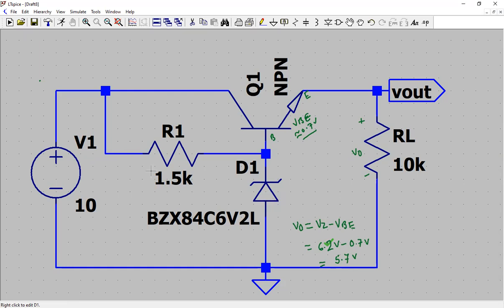So it would always be the case that when your input voltage V1, which is this one, is greater than or equal to Vz, the Zener will start conducting the current from cathode to anode, and that current is IZ. So we have seen the characteristics of it. Now, since we have constructed this circuit and values have been chosen, let us see the behavior of this circuit